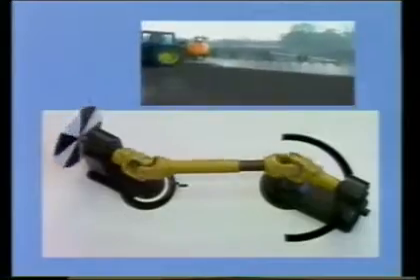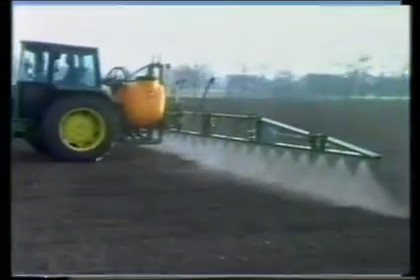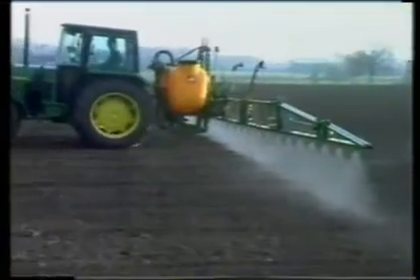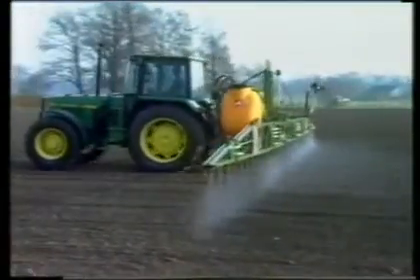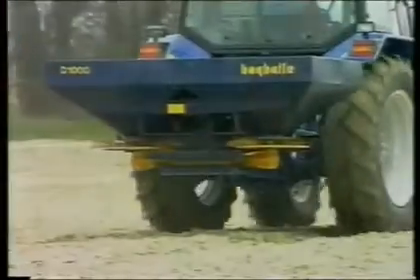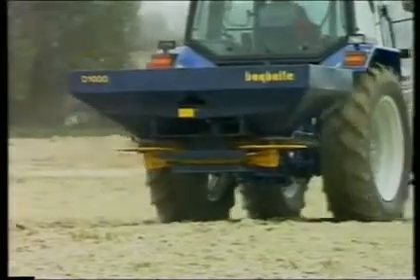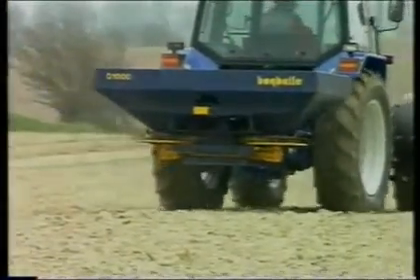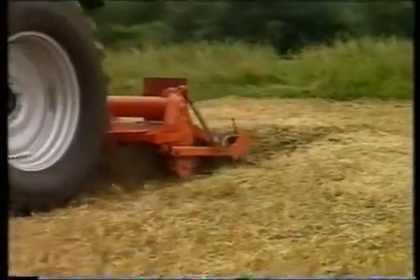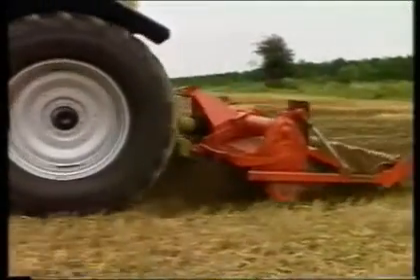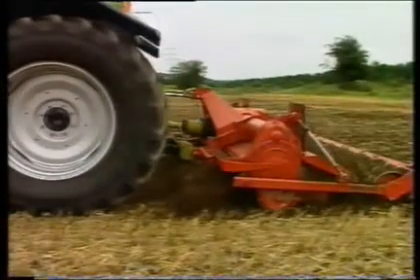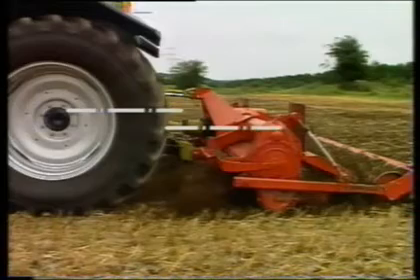With the help of Walterscheid's own computation programs, the optimum kinematics between tractor and implement can be calculated as early as in the design phase. In the diagram, lifting of the implement in millimeters is shown on the x-axis and the velocity variation in percent on the y-axis. With optimum attachment, the velocity variation during lifting of the implement is below 7%.